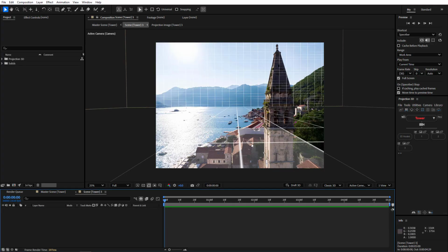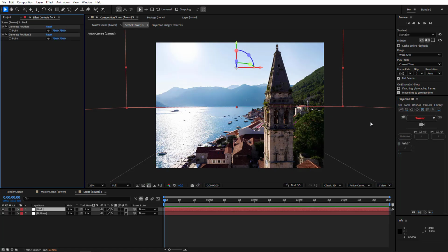Double-click on Scene 3. To create the environment, let's use the grid properties. Click on Grid icon, uncheck Left since we need only bottom and back sides, and click Create Surface using grid properties. And the environment is created.